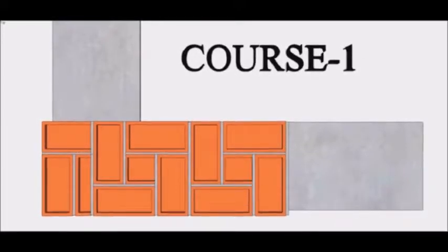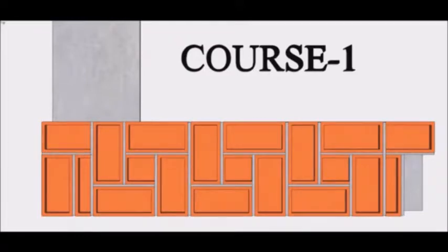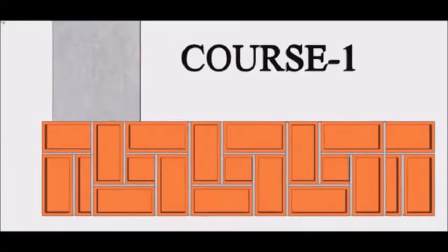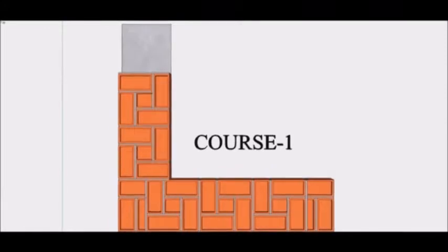Similar arrangements of bricks are made along the length of the wall. The stopped end of the wall is made by a 3/4 bat, a queen closer, and a header, which is just the mirror of the arrangement we used at the start of the wall. On the other side of the wall, a similar arrangement of headers and stretchers is made with a half bat in the middle, along the length of the wall.